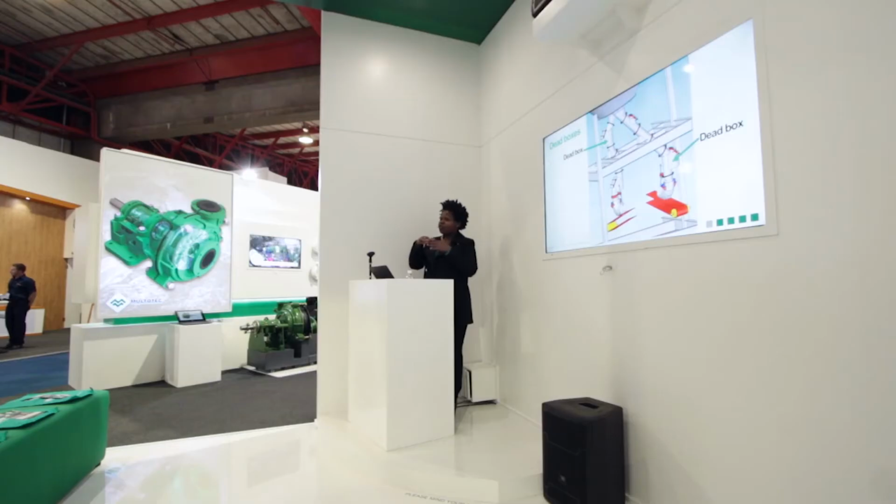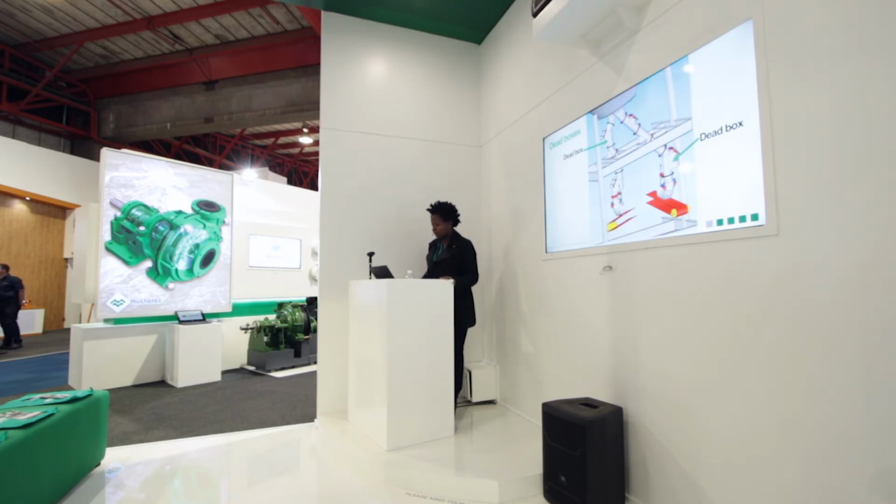But that will give the advantage that more of the material that will overshoot the trajectory will come and sit on top of the already accumulated material. So that accumulated material will act as a buffer so that you don't have direct material hitting the steel that is underneath. Right, you can also do the rectangular to round configurations.